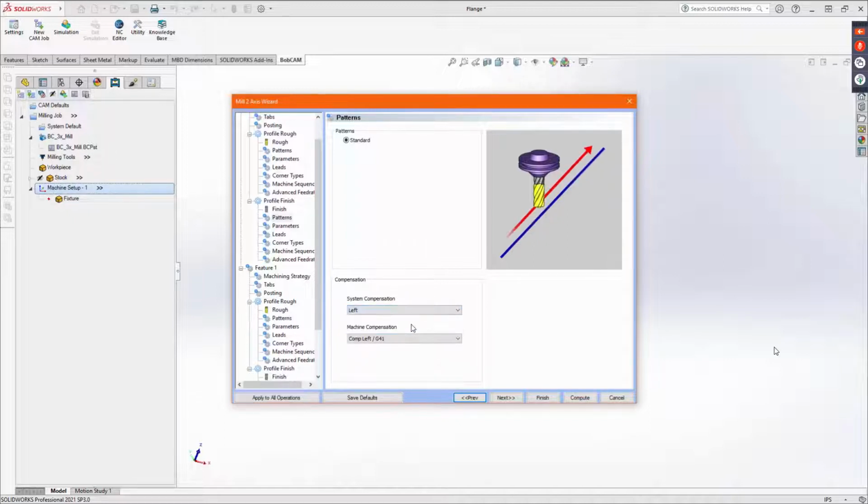Now, me personally, I use both. So I compensate for the radius of the tool, and then any additional wear, I can put that difference in the machine, and it'll adjust it for me. I used to do a lot of production cabinetry, and that worked out really well, so I always had accurate sizes, even if in the middle of the program I had to change it.